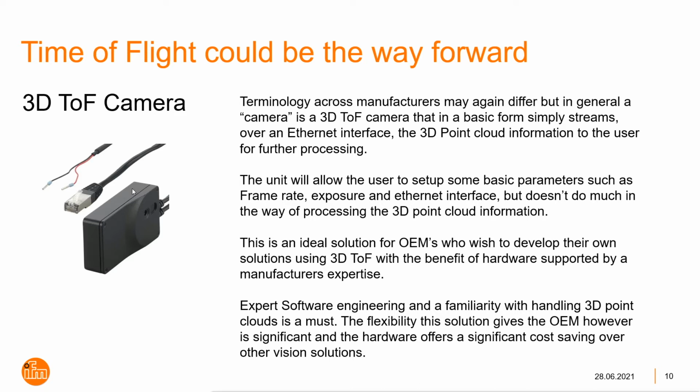But then it's going to be a raw streaming data of the 3D point cloud where you apply your own algorithms to it. There's advantages to that if you are an OEM and you're making guided vehicles, or making robotic milking machines, or your customers ask you to look at a very specific application where the standard volume, level, distance type applications written by the manufacturer just aren't going to be good enough for you. So you then move to a camera solution to allow you to do that. But this is few and far between applications. Most people can use 3D time-of-flight technology and use it in a sensor and get a very successful solution.